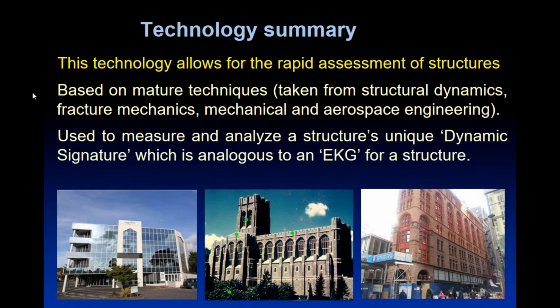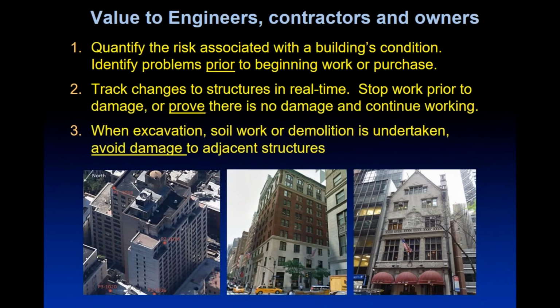Now, I said we look at different buildings. These 3 buildings are also from New York City, and bottom left we've got a 20-story condo building, and they are constructing the 2nd Avenue subway just outside, boring down underneath the building and then going through a right angle down through a tunnel to create a new subway station. Clearly, we want to know what the effect on this building is. So we've been monitoring for 2 years there, looking at the changes in the structure.